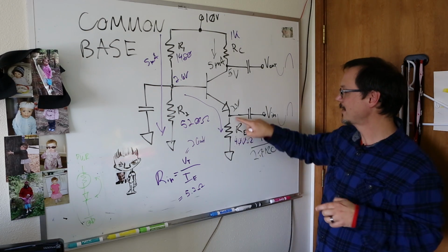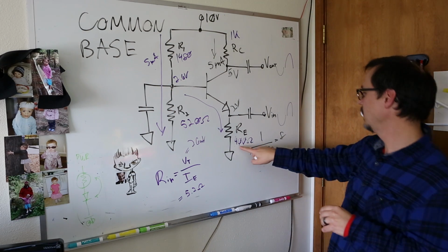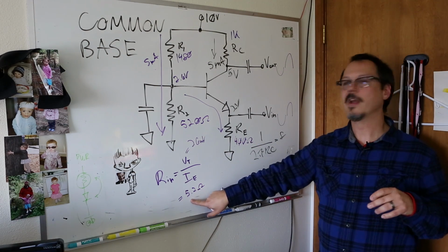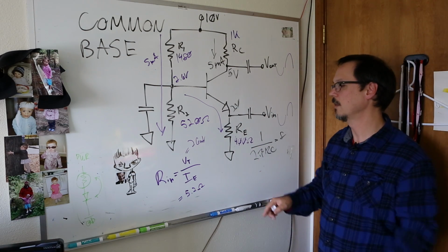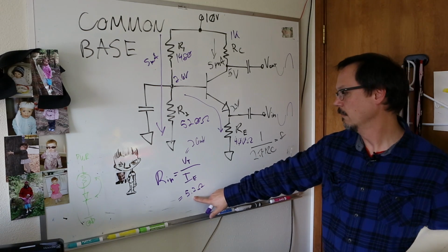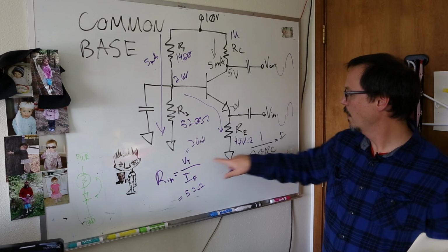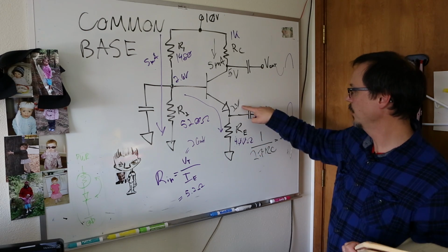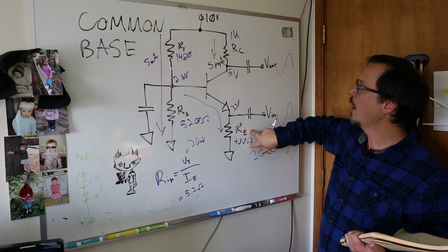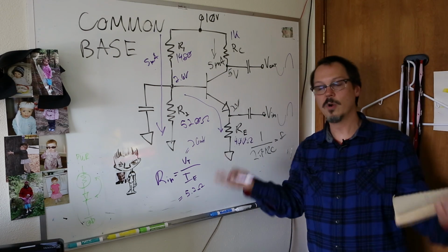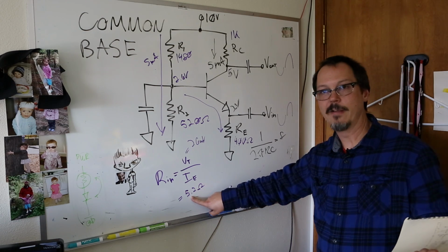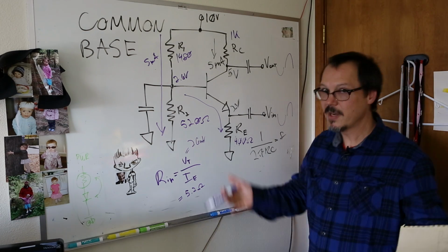This one will also not come into it because it is 2 orders of magnitude above what we're looking at. So that's not going to come into the equation either. So it's basically going to be that. Now I can improve that, right? If I chose this resistor value, still 2 volts, but if I chose this to not pass 5 milliamps but to pass 1 milliamp, for example, I could increase that by a factor of 5. Still not great, but it's better.